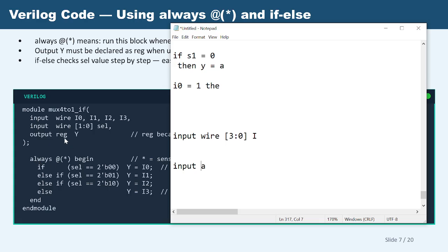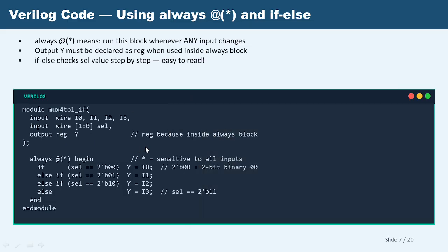So we have mentioned output reg as Y, right? Why? Look here, I will explain this reg when we write a test bench code. Just think why reg is used. Reg is used to store a memory, right? It is used to store an element. So just think why it needs to store an element. That's why we are using reg.